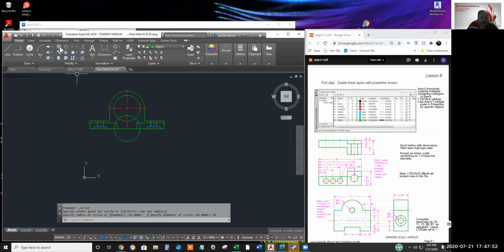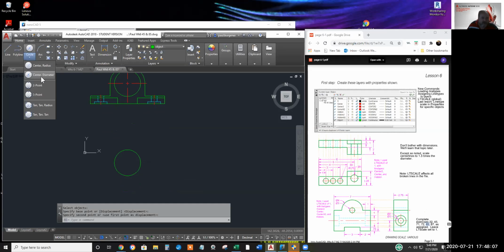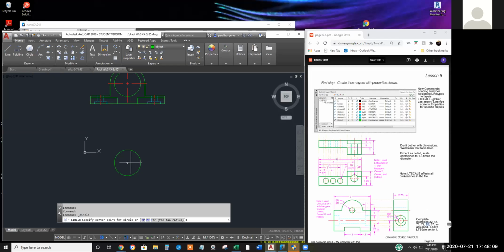Starting to rain out there. Yeah, looks like I'm going to need more white space, so fix that later. 20 unit radius on the inside, drop down radius, center 20, enter. Well, I think you're doing 86, not 85. Good point.